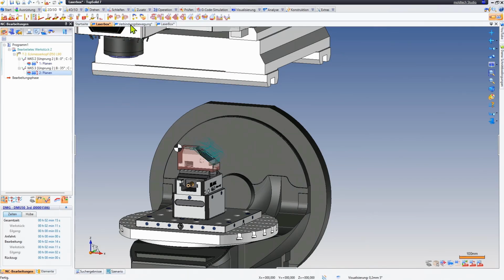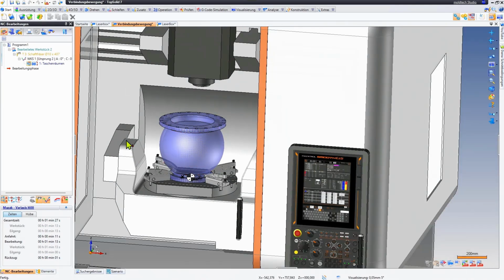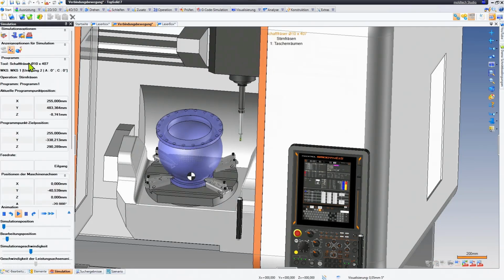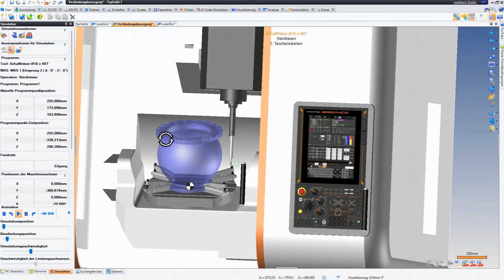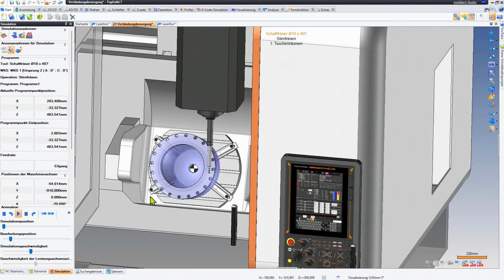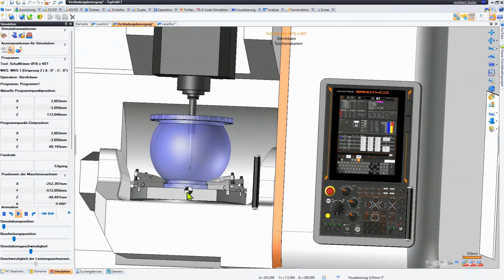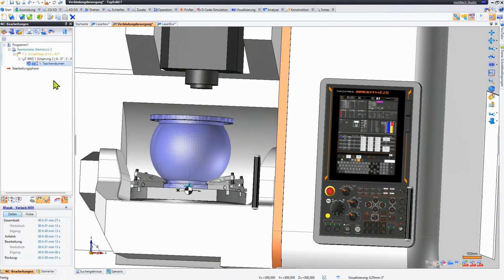A second example of the linking movement, which looks a bit more complex than in the first case. For example, when we want to machine a pocket here, where we first have to pass by the workpiece with a very long tool. Then we move the workpiece further and then plunge into such a movement. Here, for example, into this component. I can show the linking movement itself here.